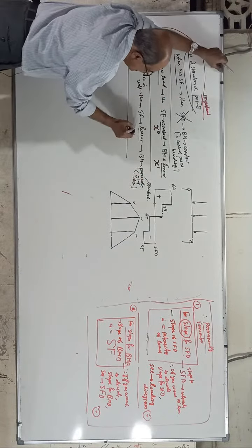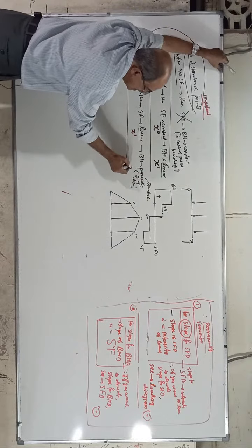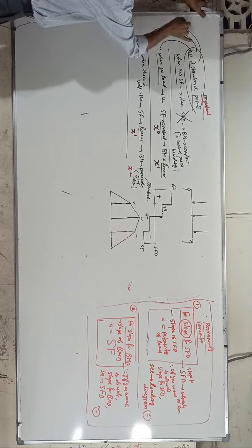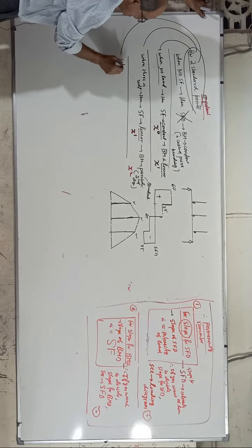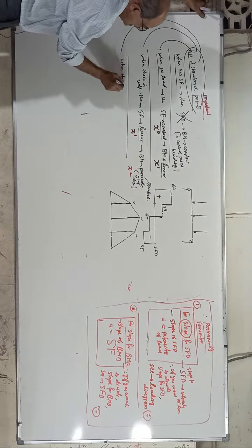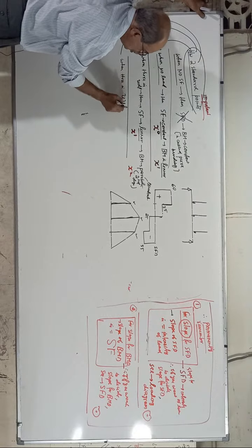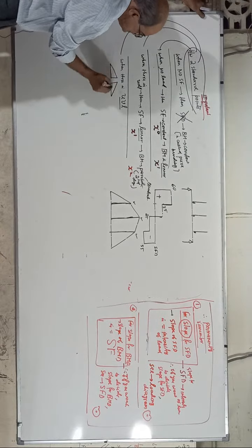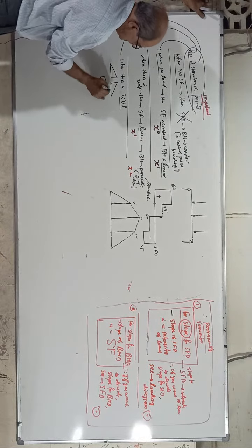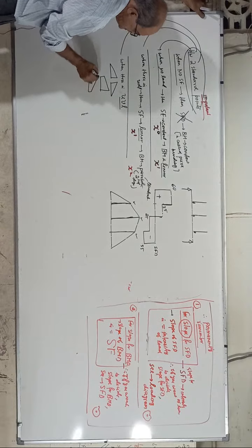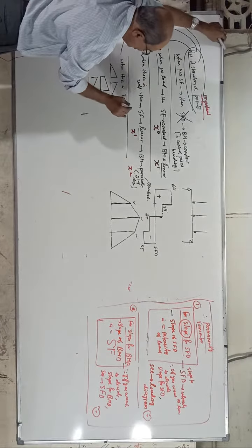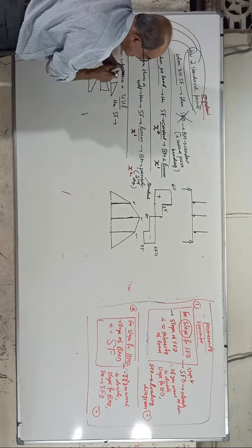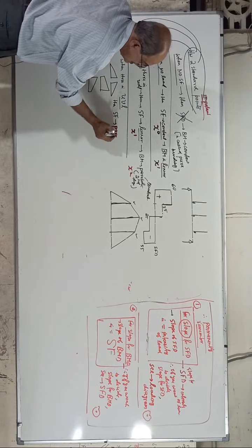That is here x power 1, here x power 2. Lastly, between two standard points, when there is UVL, which can be like this, or like this, anything, a uniformly varying load, then shear force variation is parabolic.